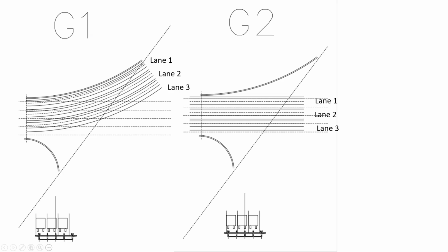For example, in girder 1, the exterior one on the far left, I push all the lanes to the left with all the trucks also as close to the left as possible. This is basically at the face of the barrier rail, 1 foot 6 inches. Start the truck, and then the wheel spacing is 6 feet.